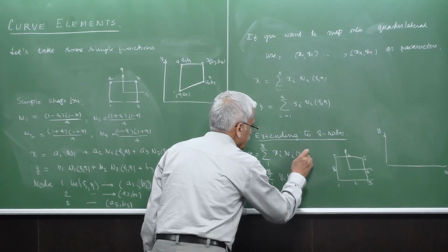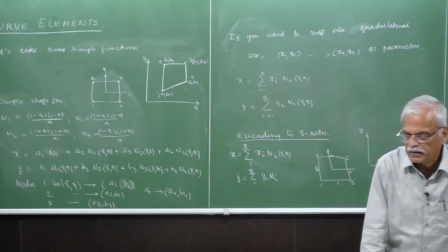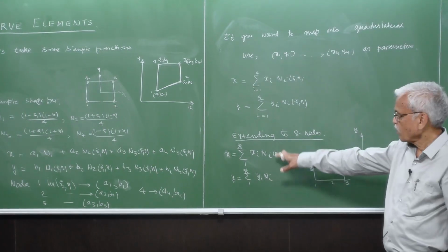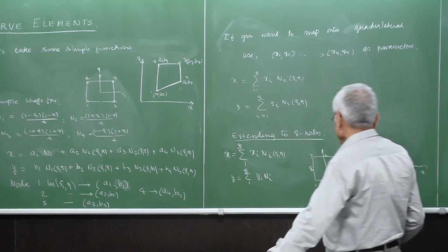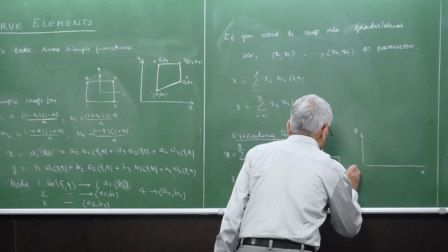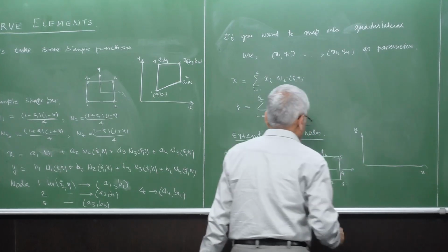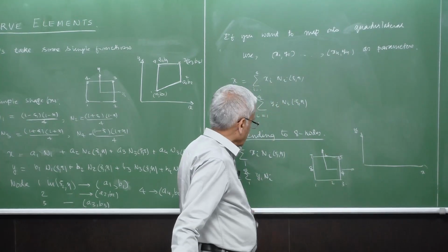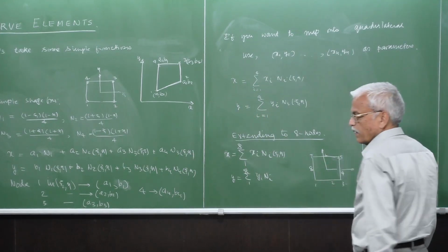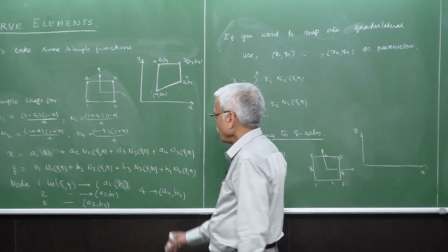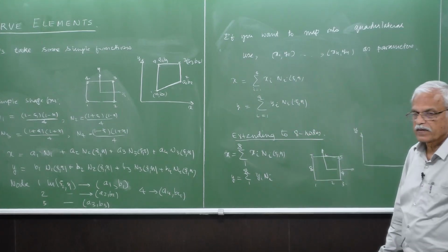So these are the shape functions which we already have seen. Say, for example, the serendipity type of shape functions. Then you can use all those 8 shape functions here. And then what will happen here? Okay, so what do you think of this one? Again, we use the coordinates of 8 nodes here. And what is your guess here? So what will happen to the quadrilateral like this one for 4 parameter representation?